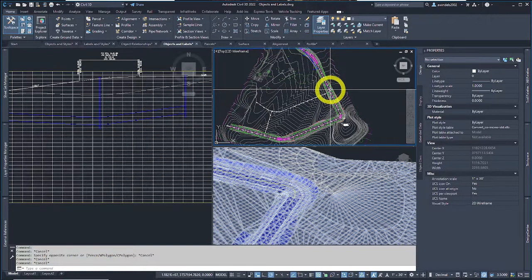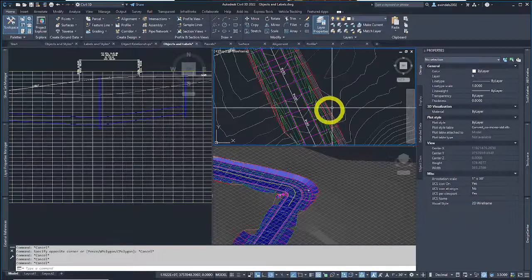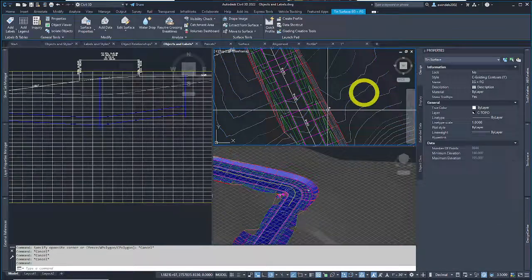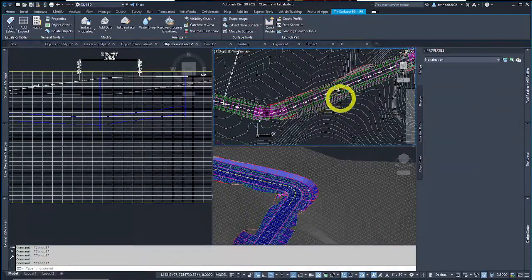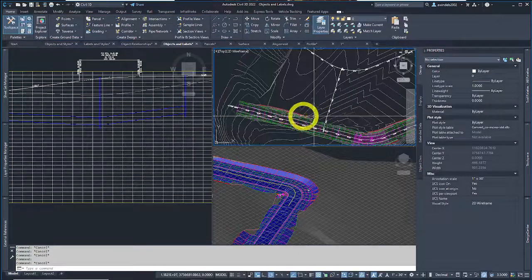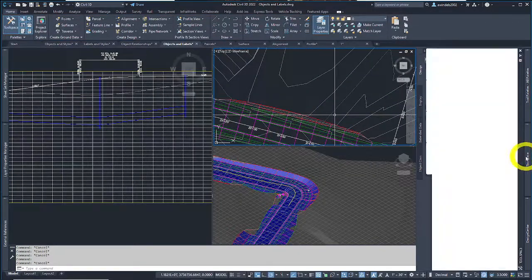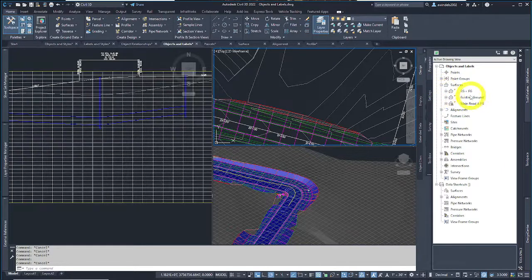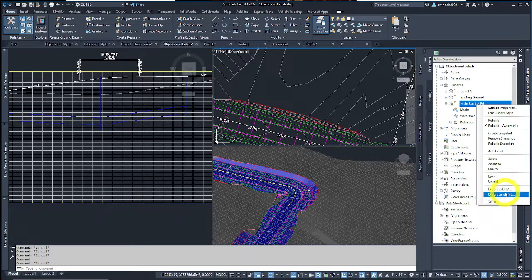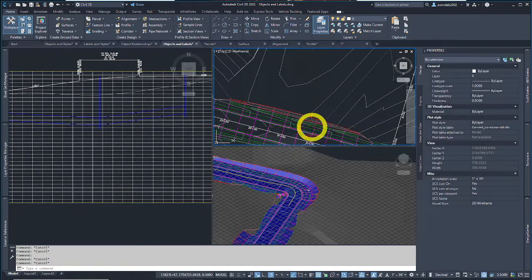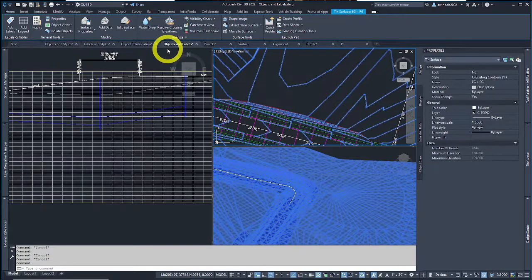Secondly, GPS guided machine control is becoming a big thing. So this finished surface, this corridor here that meshes with this existing surface, this new road coming in here, a lot of times these surfaces can be exported in various ways, which I can show you a little later. If I go to this design main road and right click it, I can export different types of files, maybe for example a DEM, digital elevation model, or a LandXML, which is a very universal file. I could pick on said file, and you have certain options to do the same thing.